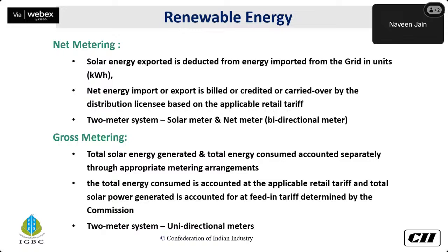So for this, a two-meter system is required. One to measure how much solar energy or renewable energy is generated, and the second is the net meter, to understand how much is exported and how much is imported. So this is basically the net metering concept.